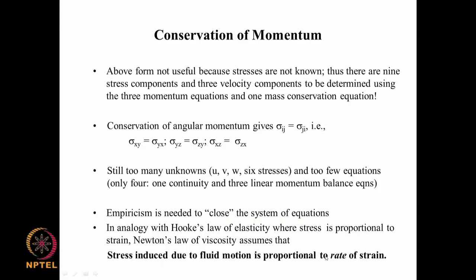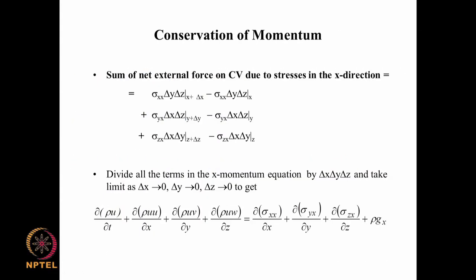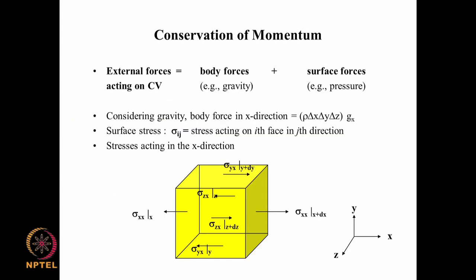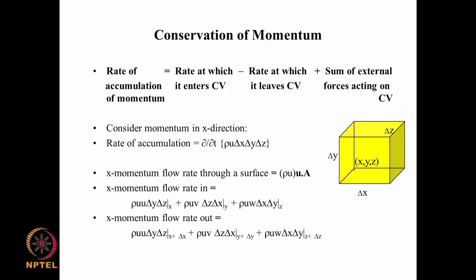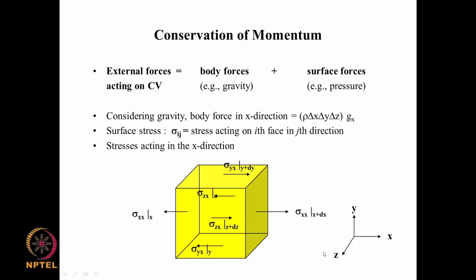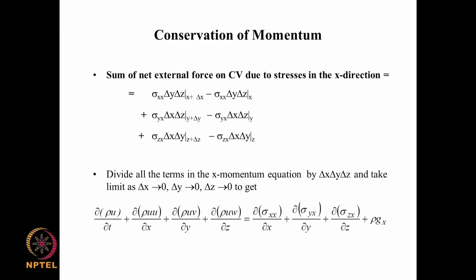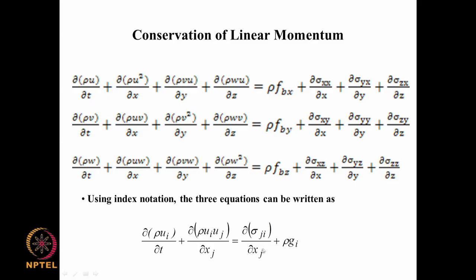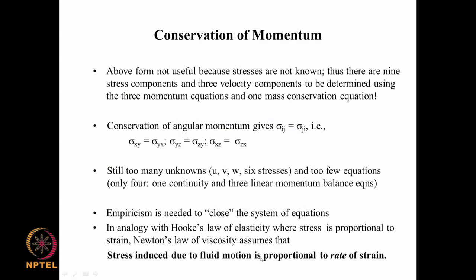What we have done in this short lecture is to pose the conservation of linear momentum in a verbal statement, and we have worked out what each of those terms are, and based on these terms we have been able to come up with a conservation of linear momentum principle, but we find that it is not sufficient, and we therefore pose the angular momentum principle, and we have reduced the number of unknowns, but we still do not have enough.